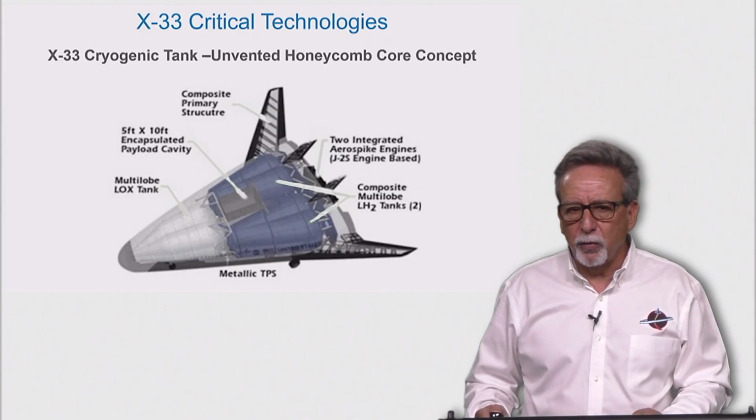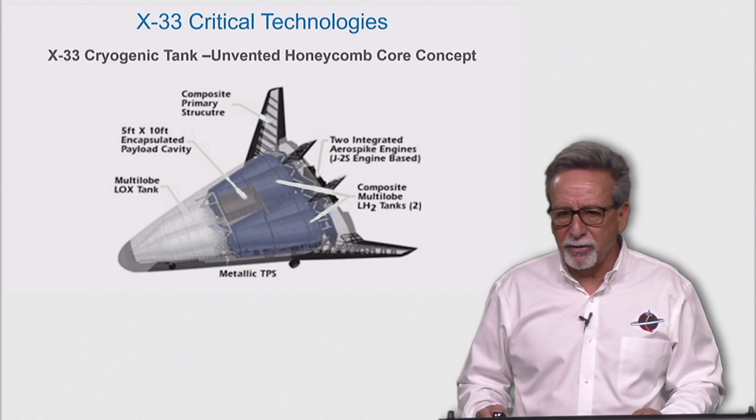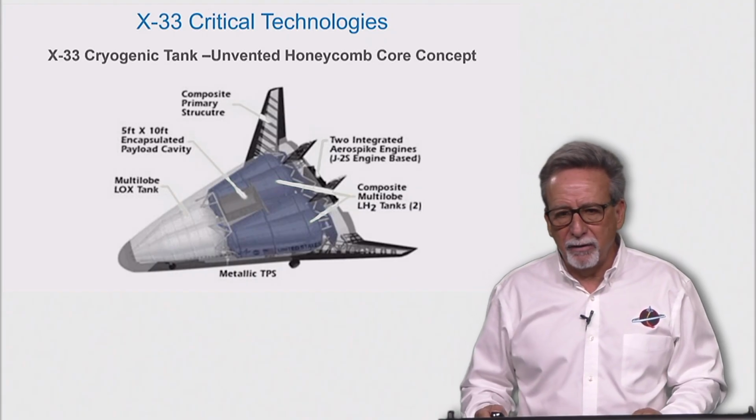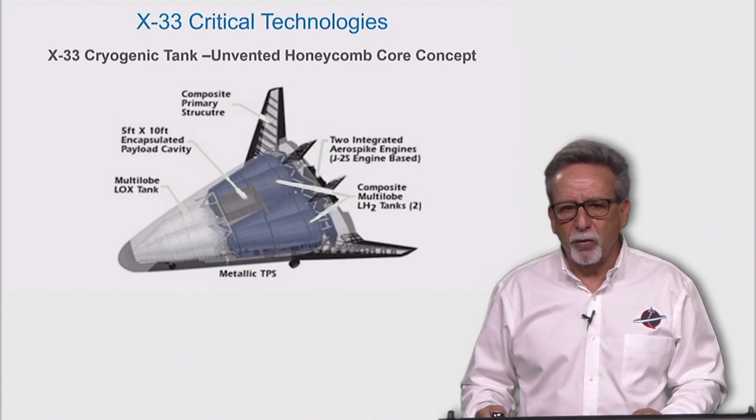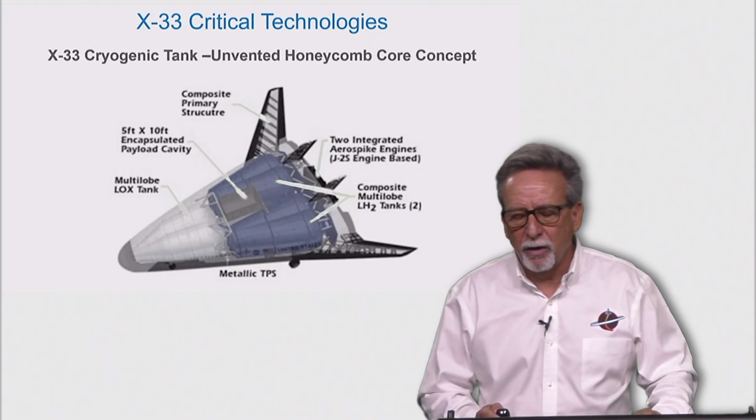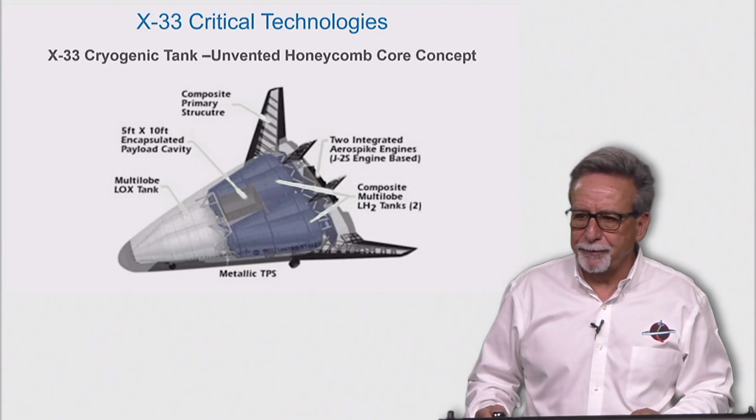One major difference between the NASA tank design and Lockheed's was the fact that NASA's design required an evacuated honeycomb to prevent possible cryopumping of liquid into the honeycomb core and subsequent rapid internal pressure rise upon heating of the structure.